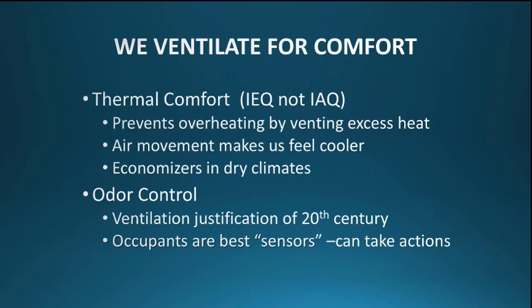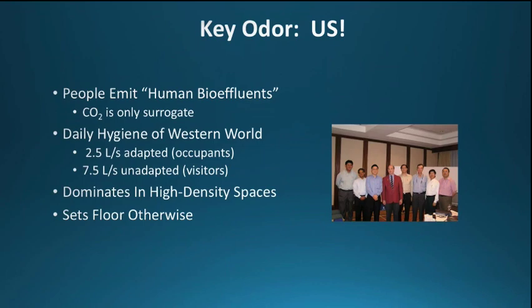Occupants themselves are pretty good detectors of odor. We know when something smells, and we know whether we like it or we don't. The biggest odor, though, that we have to deal with is us, people. We emit human bioeffluents. One of the things in that is carbon dioxide, but carbon dioxide itself is not a contaminant of concern at the levels that we talk about things. It's only a surrogate for human bioeffluents. And we learned through data at Kansas State and in Denmark that 2.5 liters a second per person is enough to keep adapted people who've been in the space for a little while,